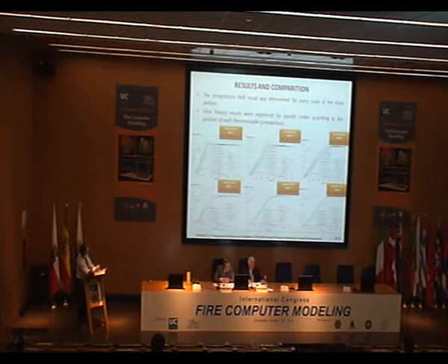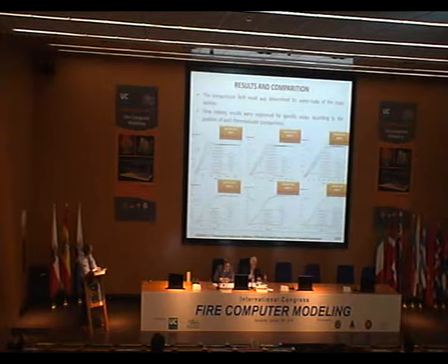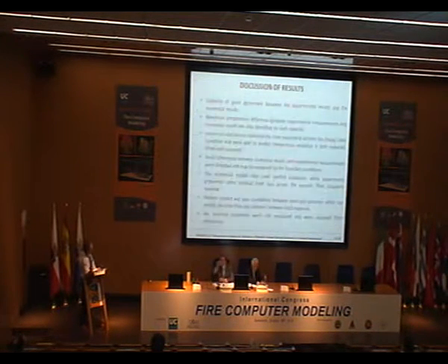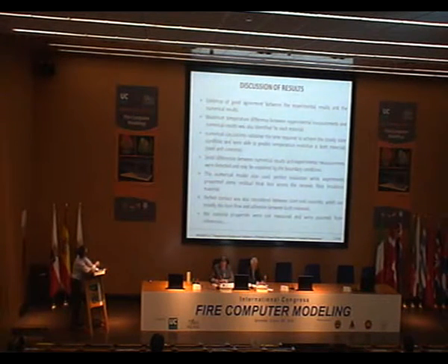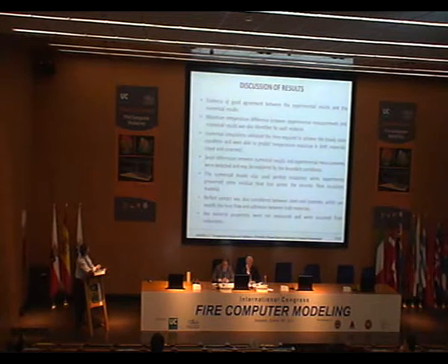So the time series results were presented for specific nodes according to the points of each thermocouple position. So let's present some discussion of the results. So there is evidence of good agreement between experimental results and numerical results. The maximum temperature difference between the experimental measurements and numerical results was also identified for each material, for steel and concrete. The numerical simulation validated the time required to achieve the steady state.